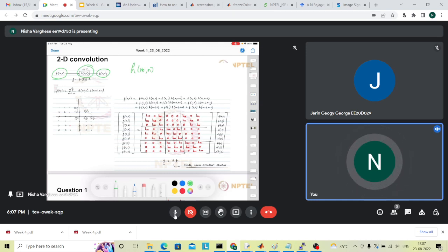So it can be considered as light passed through a lens, and some output will be given at the image plane, g of mn. And we have already proved that a lens is a linear space invariant system, so we can use convolution to get the output, the convolution of input and impulse response.